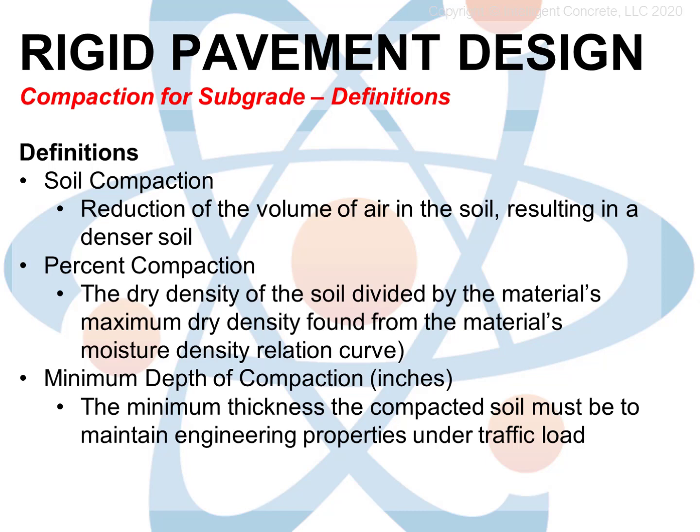Soil compaction is the process of compressing the soil to force out air and, in some circumstances, excess water. Compacted soil is much more stable than uncompacted soil, as pressure forces out air, making the soil more dense, and compact, meaning additional compression or settlement is difficult to occur. The percent compaction relates to how close to a theoretical maximum degree of densification can be achieved.